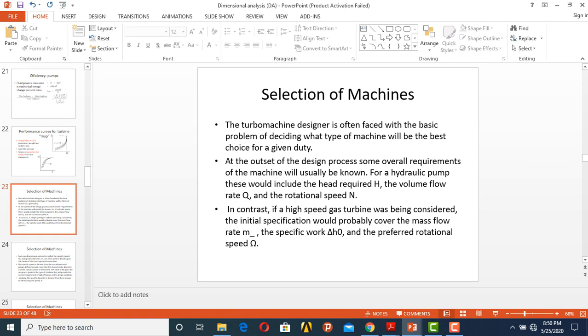When I say duties, I imply what is your aim. In the case of a pump, say you are working underground in the mines, and then the machine underground has a fault or has failed. And then your supervisor or the head of the section requires you to find a replacement for that machine. Hence, first and foremost, before you go on the market to look for a replacement, an engineer sits down first and puts down what the duties are.